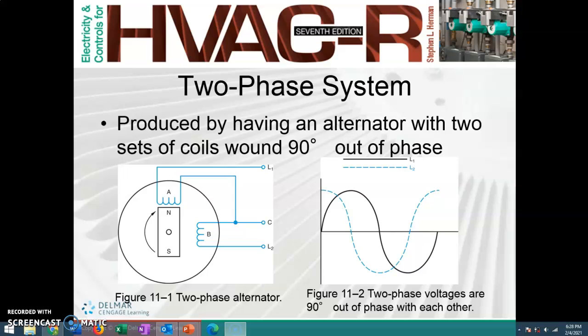If that were the case, you would just have a constant magnetic pull. The magnet would just go to that, and it would seem like a locked rotor. Nothing would spin. So we trick the motors into thinking there are two phases, or we split the single phase, hence split phase motors for the title of this.